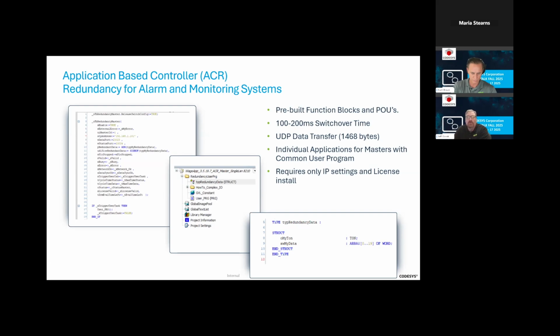We are looking at trying to see if we can use jumbo frames, and jumbo frames are around 9,000 bytes, which would be nice to have a lot more data going back and forth. But you also need a gigabit switch capability, or gigabit capability on your Ethernet ports on your devices. So we're looking at those PFC300s.